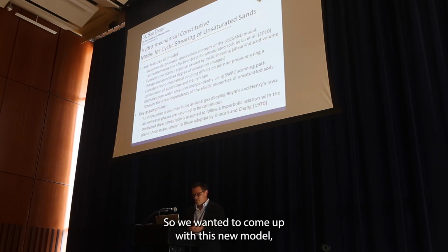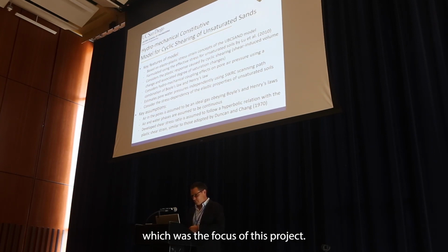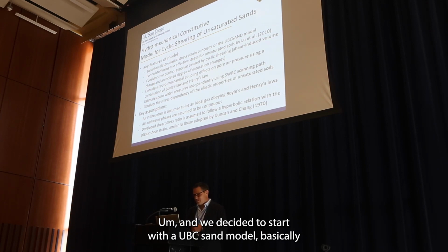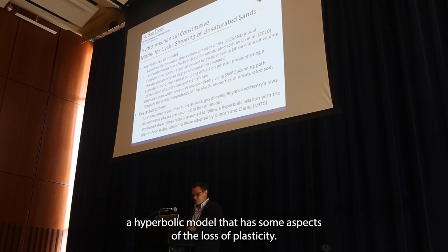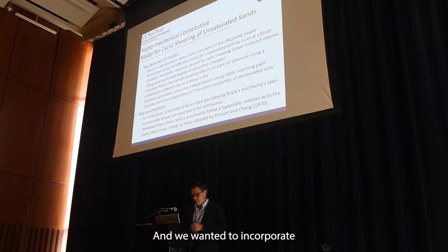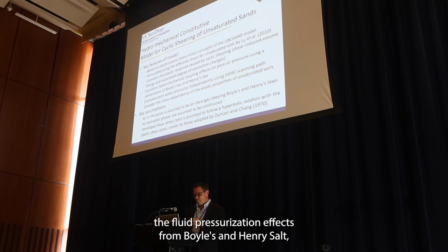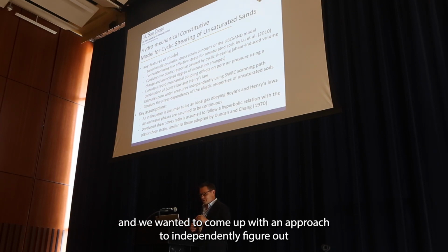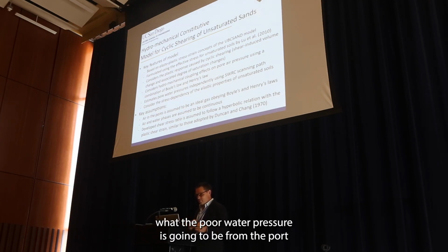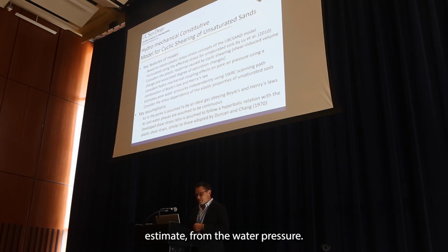So we wanted to come up with this new model, which was the focus of this project. And we decided to start with the UBC sand model, basically a hyperbolic model that has some aspects of elastoplasticity. And we wanted to incorporate the fluid pressurization effects from Boyle's and Henry's law. And we wanted to come up with an approach to independently figure out what the pore water pressure is going to be, estimated from the pore air pressure.